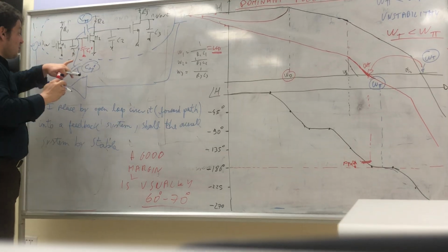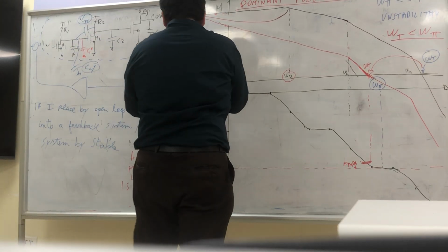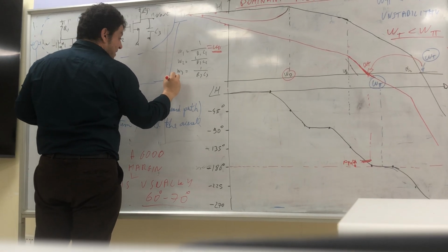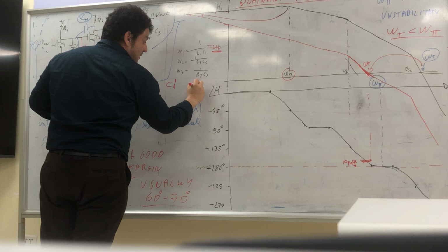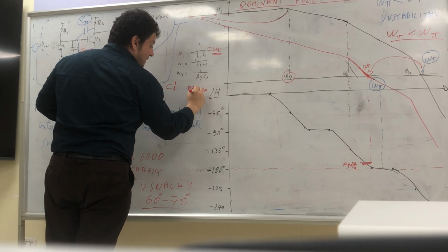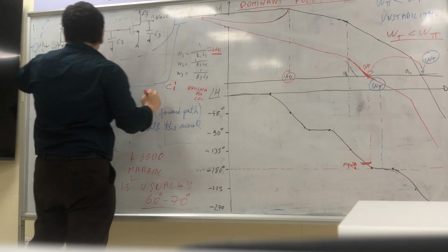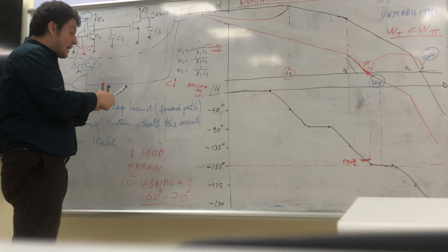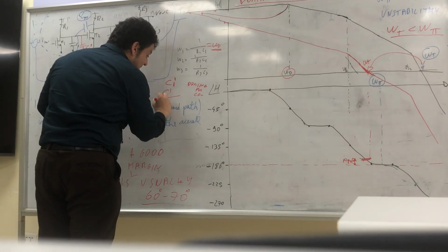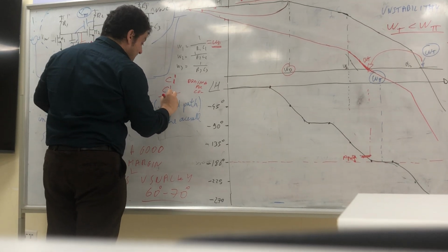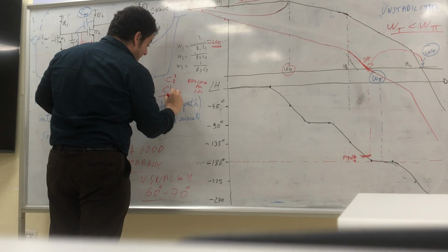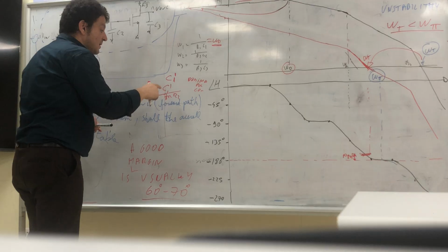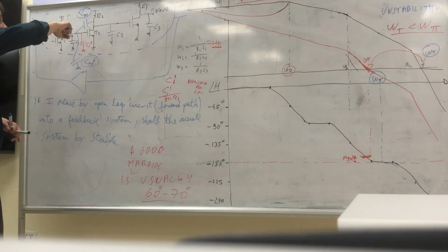So for instance here, to move the dominant pole you add the capacitance C1, the dominant pole compensation. With the Miller effect, you can get the same effect with a capacitance that is smaller by the gain of the stage, gm RD2. Why? Because this is affected by the Miller effect.